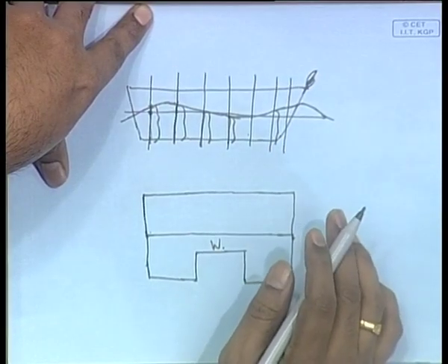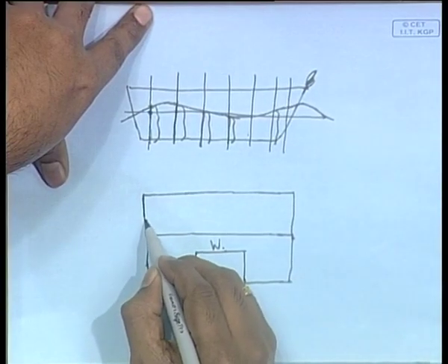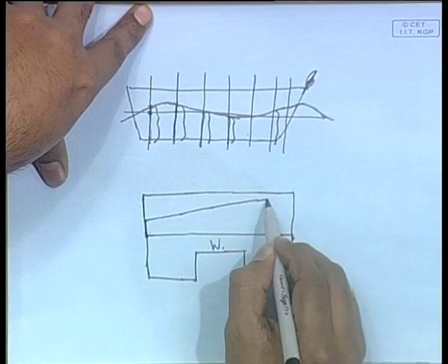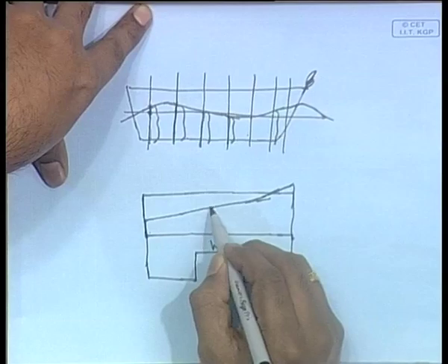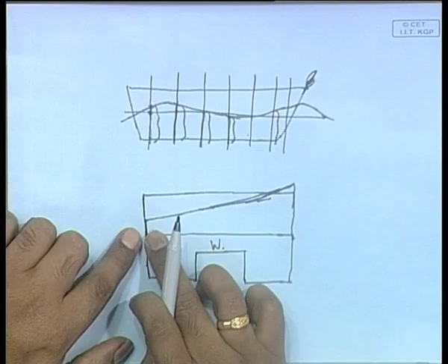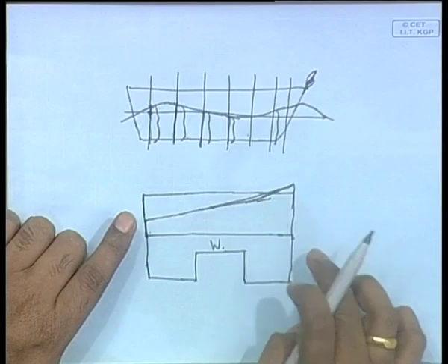For a box shaped barge that is in a trimmed condition, it will be like this, linearly varying. So, for a trimmed condition, its buoyancy will be a varying function like this. So, buoyancy will be different.